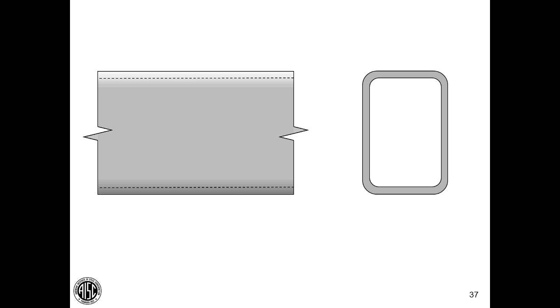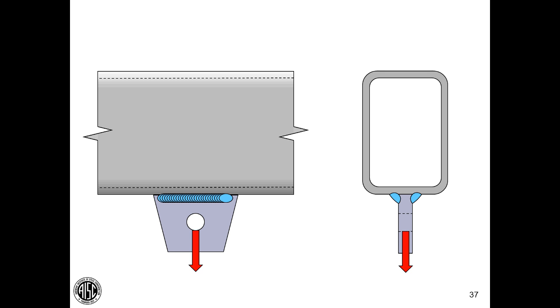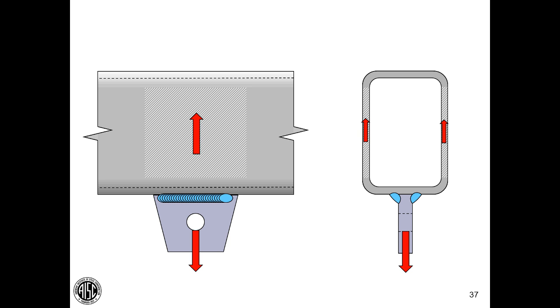And if we add a lug underneath the square tube, I hope all of you by now recognize we have a problem, because the parallel portions are the webs, if you will, of this tube. And so even though we might have a weld that's strong enough for the application, we don't have a good load path for the force to be transferred into the member that lies parallel.